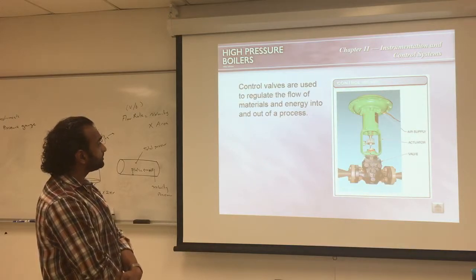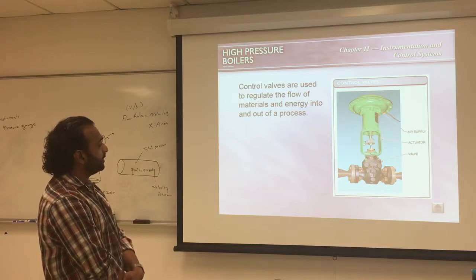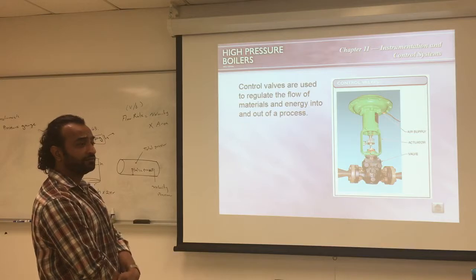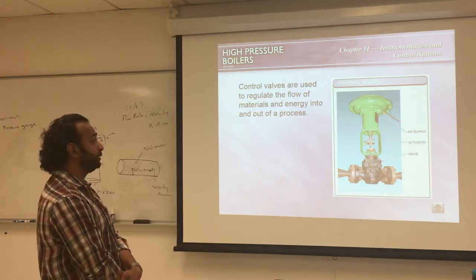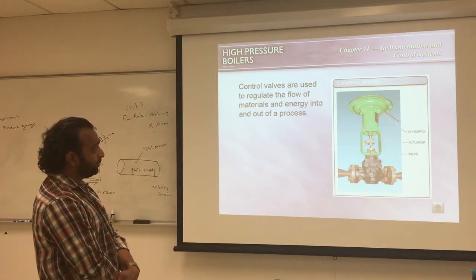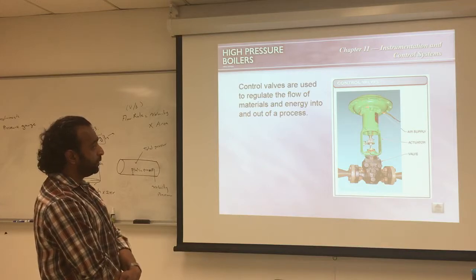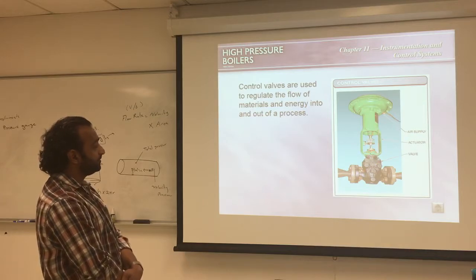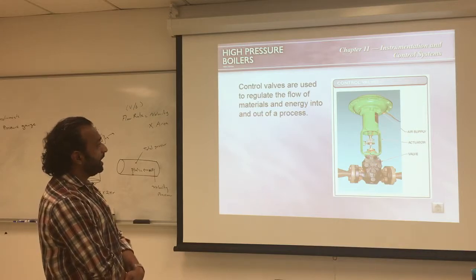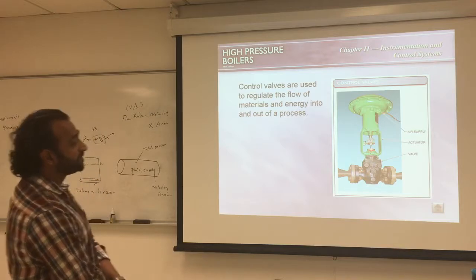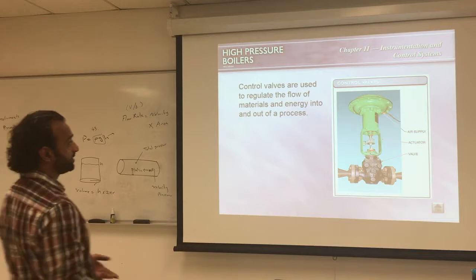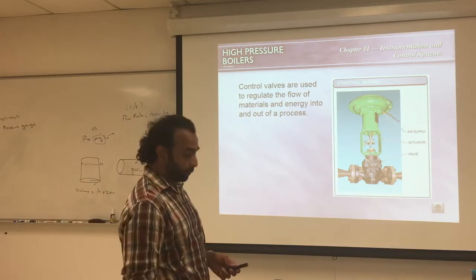Control valves used to be pneumatic, where basically we use pressurized air to open and close valves remotely, so we don't have to go there and do it manually. So it's composed of an air supply here, which exerts some pressure on a diaphragm, and the actuator here will close the valve or open it. A lot of them are still in the field, but they are being replaced by motorized valves because they're more precise and easier to work with.